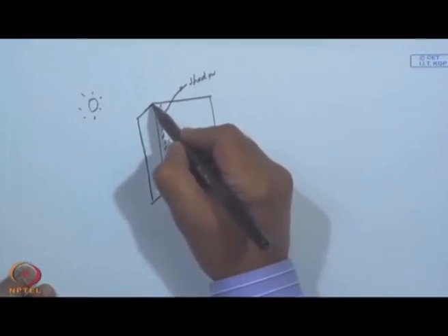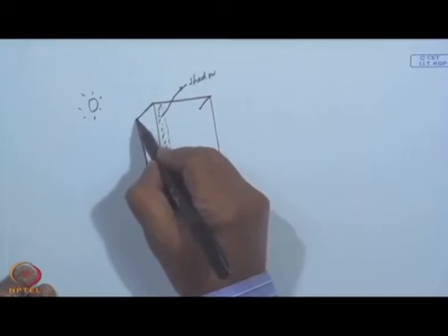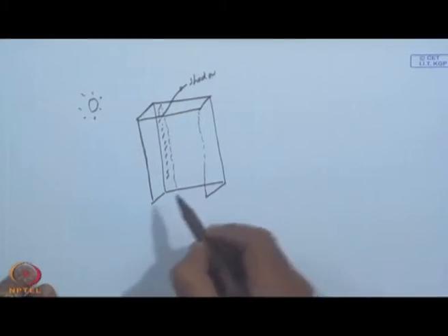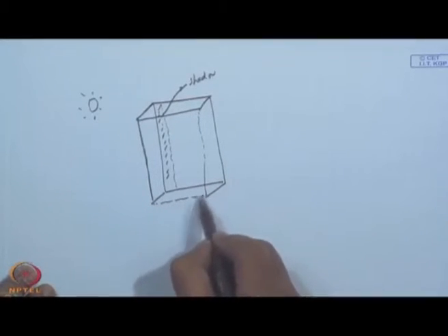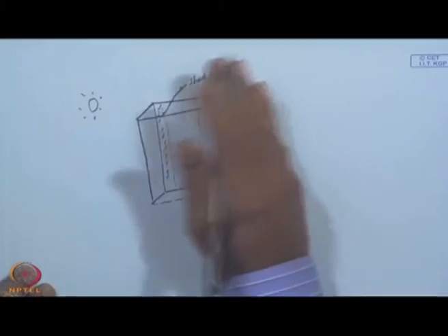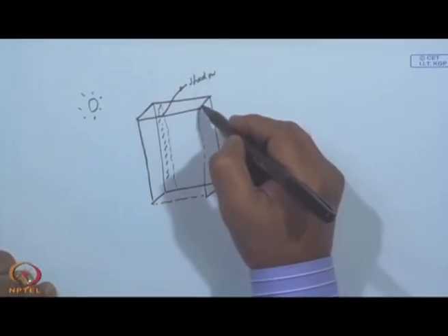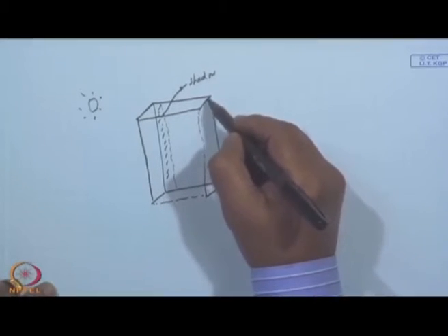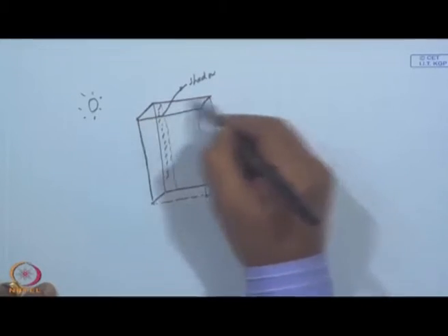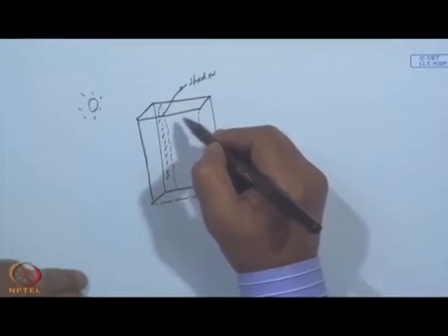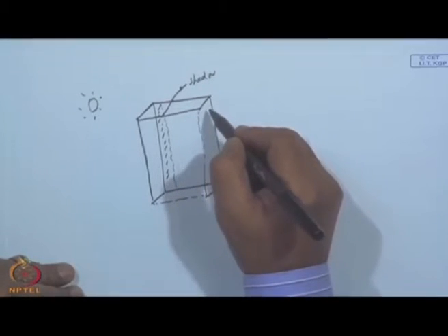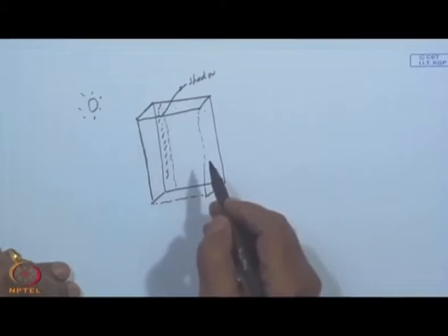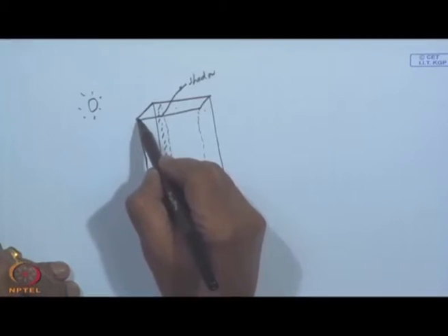So, if you have an overhang and two wing walls, and bottom is not necessary, but usually that makes it a box type window, there will be pretty good coverage. I have not yet exactly made the calculations, but I suspect that if you have wing walls associated with the overhang, you may treat the overhang as if it is infinitely long, because it is either shaded by this or this. So, that is a different issue. And now similar concept can be extended.